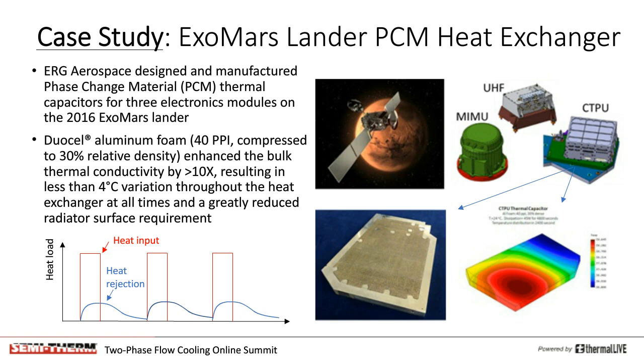However, much higher peak loads can be accommodated using a phase change material, typically a paraffin wax, that absorbs the high heat load as it melts and then solidifies or recharges during periods of lower dissipation. This cycle is illustrated in the notional plot below. The trouble with most phase change materials is that they have a very low thermal conductivity.